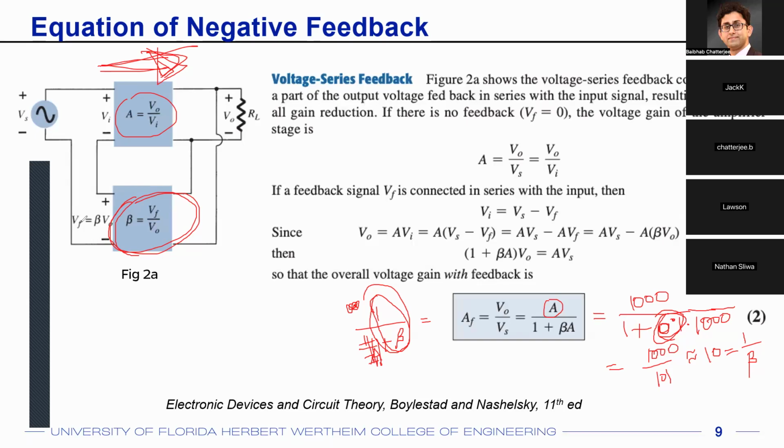They are generally because of some deterministic reason, that, oh, somehow I did a higher amount of ion implantation, or somehow my temperature was higher than what it should have been during the fabrication of those resistors. But it's the same for all those resistors. So in a batch, generally manufacturing variations go in the same directions. They are not really random.